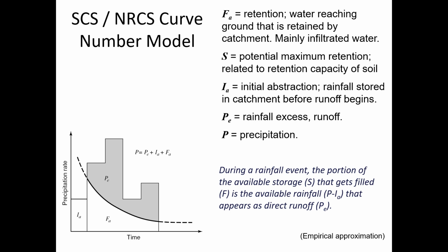What do you mean? Like, initially when it starts raining, there's no runoff. It has to go into the ground first, and the ground has to become saturated. You're right. Yeah. So you're definitely correct about that. There hasn't yet been any excess. So why not? Well, remember that this is the precipitation amount. So the precipitation amount was less than the infiltration rate. And so you're only going to see excess when the precipitation rate exceeds the infiltration rate.